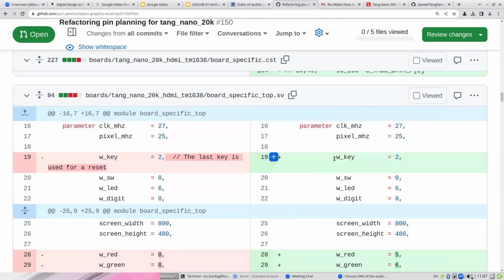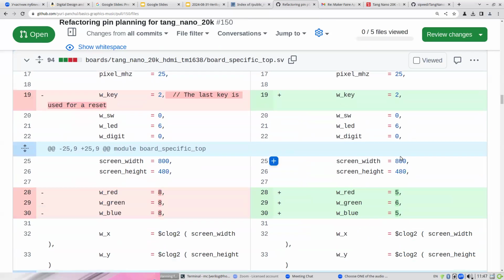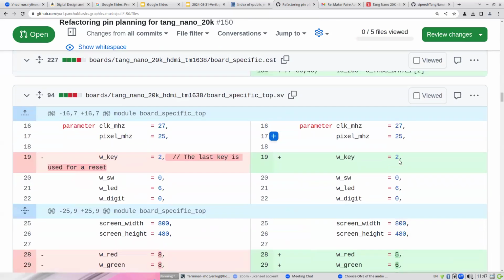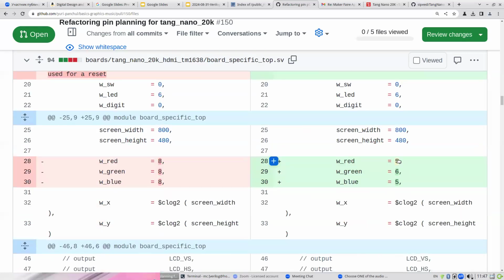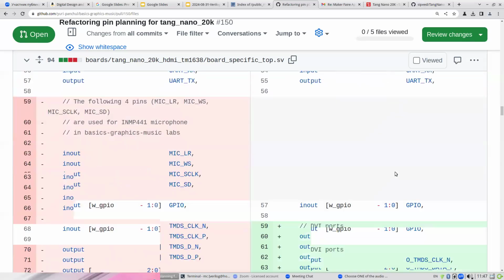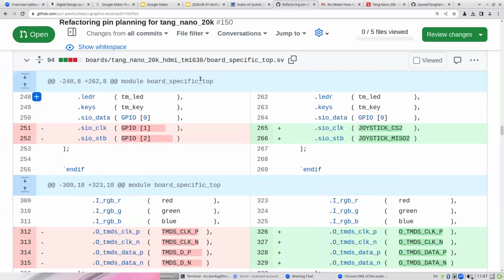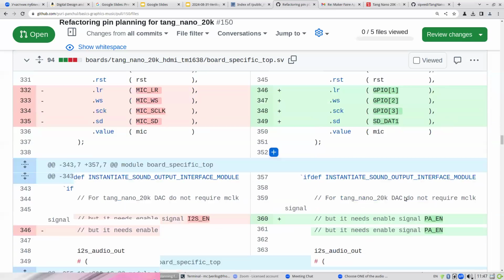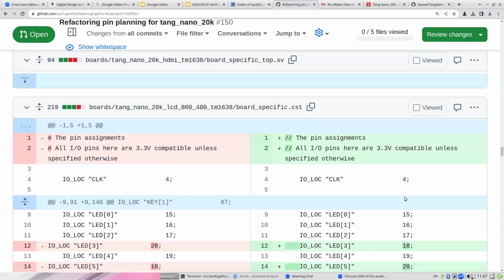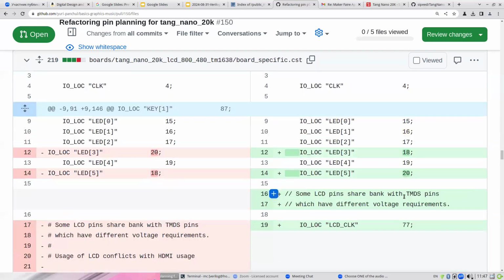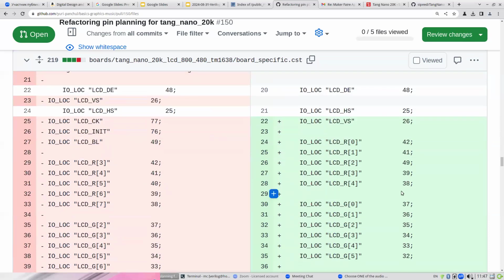Okay, so this looks fine. So we have two keys and two native keys. One thing, yes, Alexander, but HDMI has 8 bits per channel, so you should put 888 here actually, and LCD has 565. I think you got confused and put 565 into HDMI, but we need to put 565 in LCD. For HDMI, we need to put 8 bits per channel.